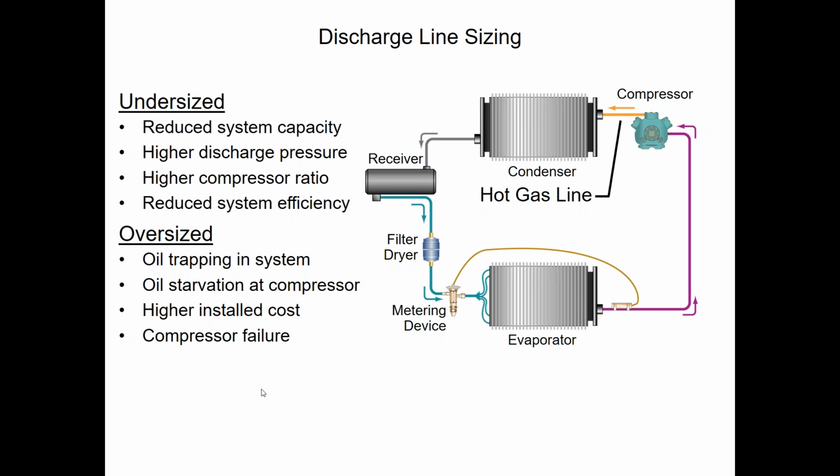So these new compressors, and I say new, they're not new, but these scroll compressors, the hermetic style compressors, don't have the volume of oil that the old semi-hermetics used to. The old semi-hermetics used to have anywhere from a gallon to a gallon and a half of oil in it, and then some. Nowadays, we don't even have a gallon in these hermetic compressors. So we need to get as much back as quickly as possible. And that's why these line sizes are just so critical on these units.